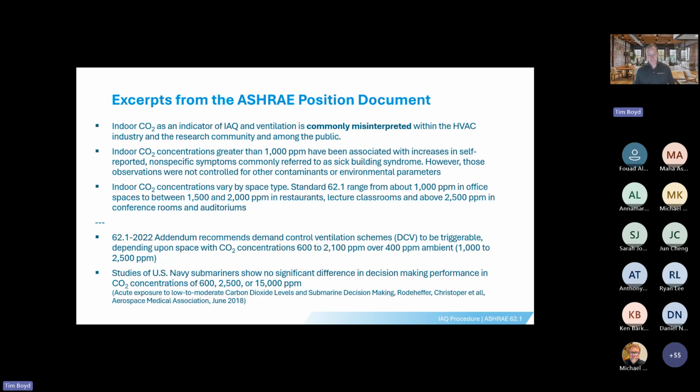Notice the last bullet. There's a study done by the U.S. Navy for the submariners in those vessels, and what they found was there was no significant difference in their decision making or their performance, even as high as CO2s of 15,000 ppm when the contaminants were already handled. And so that really demonstrates that it's a proxy gas, a tracer gas, it's not a real fundamental air quality issue.